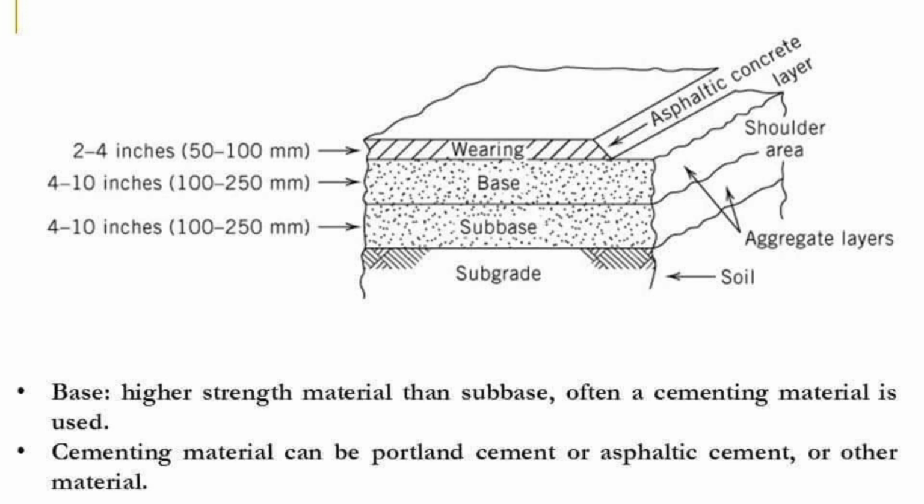But for proper design, you have to conduct a traffic study from which you will get the axle load in the form of ESALs, and then you have to conduct the soil tests from where you will get the CBR value.